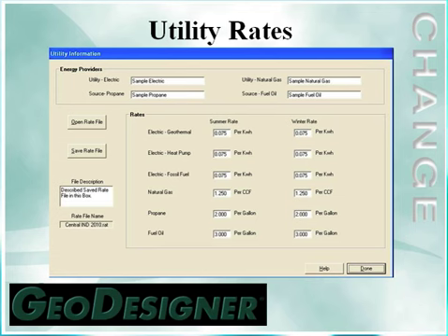I want to caution everybody when we go to put in utility rates that we actually take, and it's helpful if the consumer will share the utility bill with you, look at what we're actually paying on the utility bill and divide it by the consumption. How many kilowatt hours we use during that month, and divide it by the bill and get our true cost. My rates here in central Indiana that I have on my utility bill show about 6.8 cents per kilowatt, but when I look at the actual delivered charge, including taxes and all the other fees associated, I'm at 7.5 cents a kilowatt. Same thing if I'm on natural gas, propane or oil.